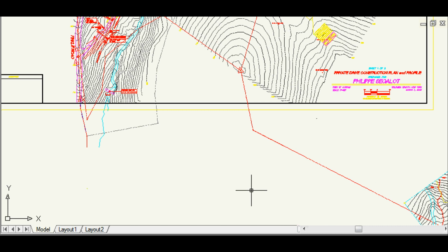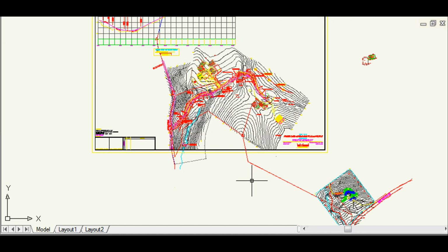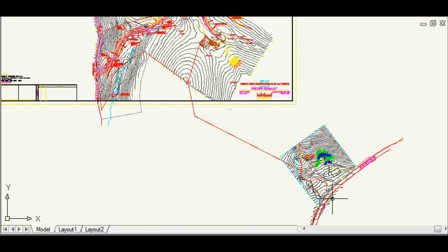Anyway, we were talking about baseline, and I was explaining baseline to you. So I'm going to provide 2 different examples so you can have a good concept of how surveying works. I chose this job specifically because it's a great example of a job where 2 different pieces of land are tied together that we need topographic data on, but we don't need topographic data in between them. So you'll see here that these jobs are tied together with what's called control.